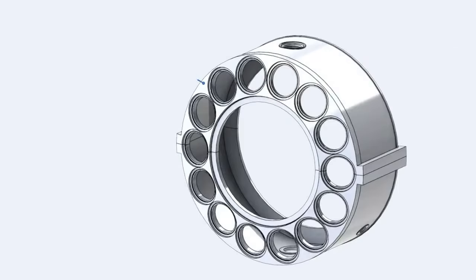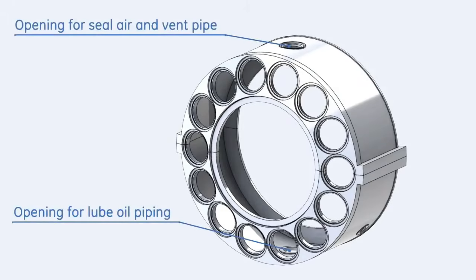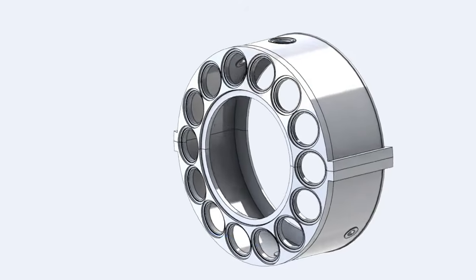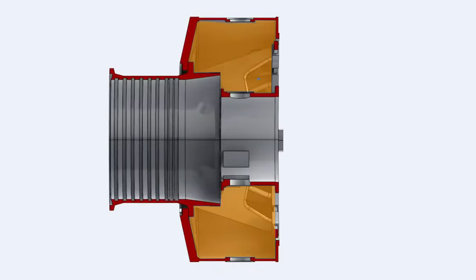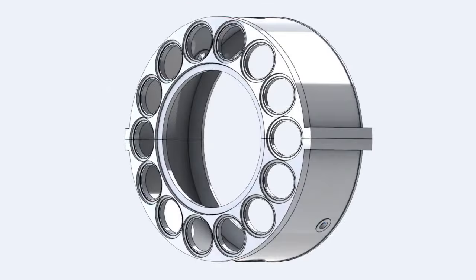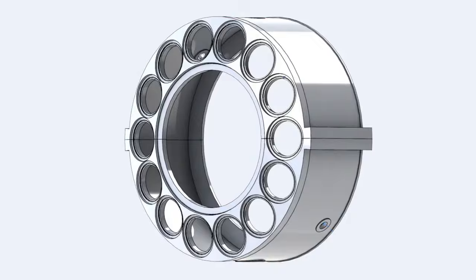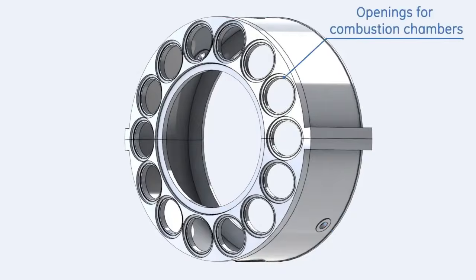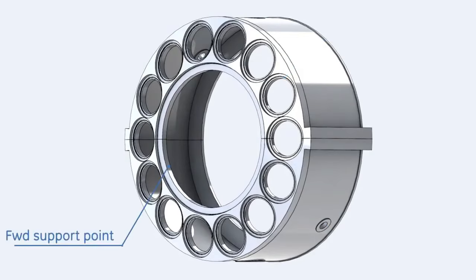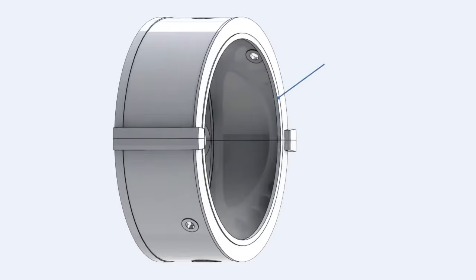The combustion wrapper is a fabricated horizontally split casing that encloses the combustion system. It provides a supporting surface for combustion chamber assemblies. The wrapper forms a large plenum, which receives the compressor discharge air. This air is directed upstream to the combustion chambers. The forward face of the wrapper is slanted at 13 degrees from the vertical and contains machined openings to mount the 14 combustion chamber covers. The wrapper is supported by the compressor discharge casing and the turbine shell.